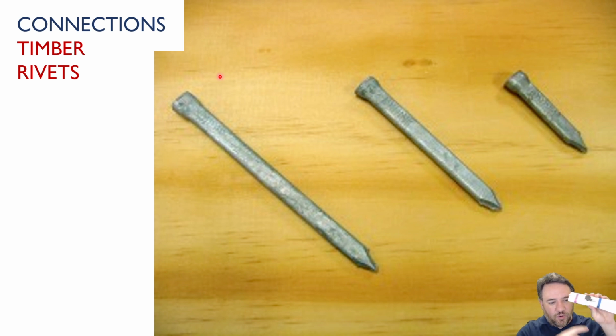But really, the more that I can spread the fibers apart and stick the fastener in between them, the better, because then I get a really high friction in between the two. Okay, so if I use a round one, it's going to be a bit more difficult. If I were to use something flatter, let's say I have a flat cross section, then I can fit it more easily in between those fibers, which means I don't have to push those fibers so far apart.